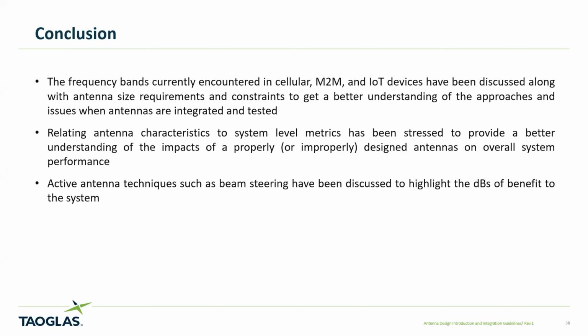What kind of gain can you get out of a 4-element array at 28 gigahertz? Not much. Back in 2017, going to some conferences, they were talking that they would like at least 8.5 dBi of antenna gain on the smartphone. With 4 elements, if you could maintain 5 dBi out of a patch, you're looking at 3 dB when you combine 2, another 3 when you go from 2 to 4, so 11. But you've got losses at those frequencies, so I think with the 4-element array they may be able to get somewhere between 8.5 and 10 dBi.